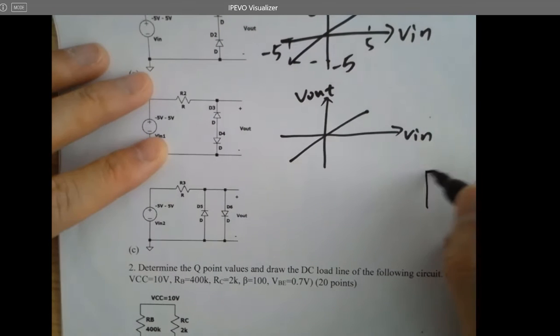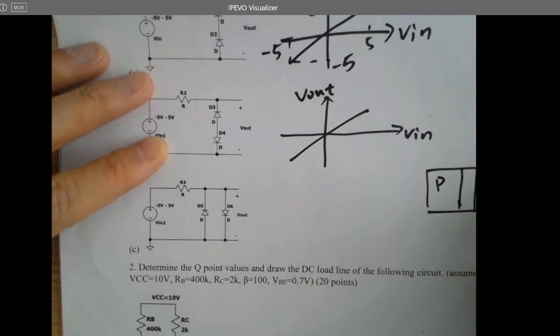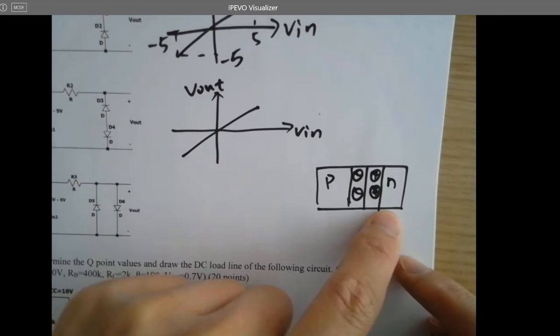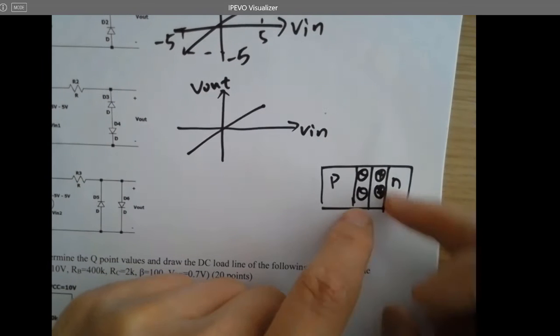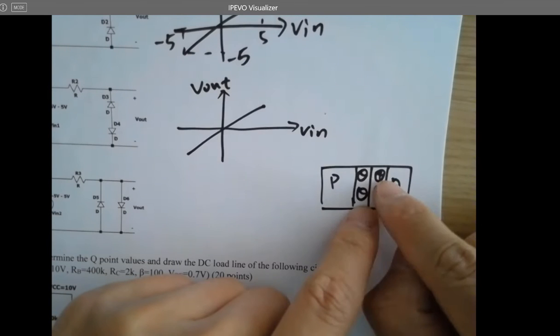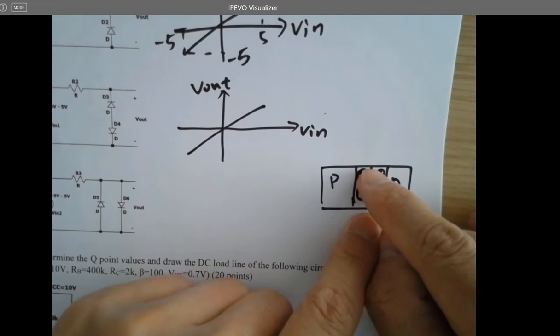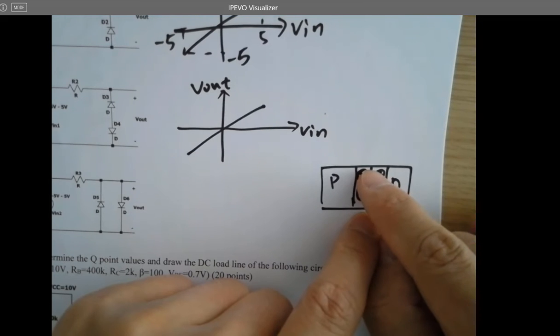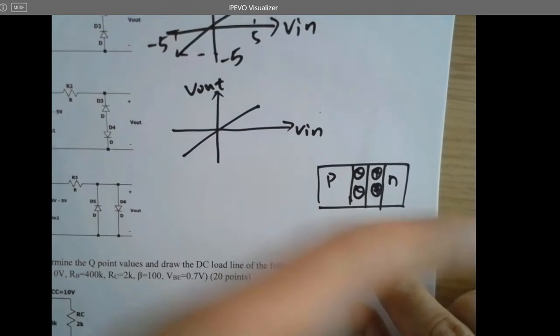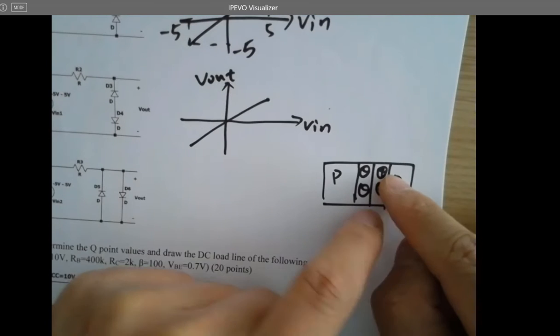So remember the p-n junction. Let's try to understand this properly. Everybody knows there will be a depletion region here in the middle of the p-n junction, and the holes diffuse to the right side and the electrons diffuse to the left side, and this forms the depletion region. Why? Because the electrons flow to the left and fill into the holes, so it becomes negatively charged, and the other direction as well. The holes come over and combine with the electrons.